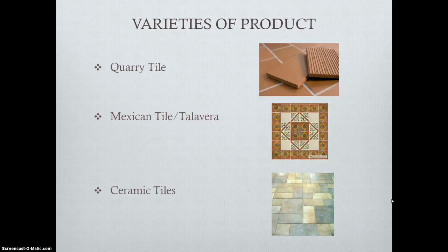There are a variety of products among ceramic tiles, one being quarry tile, which is made from either natural clay or shale. Quarry tile is similar to brick in material, performance, range of colors, and methods of installation. Moisture, oil, acids, or other chemicals do not typically affect quarry tiles. Quarry is highly durable and used both in exterior and interior applications.